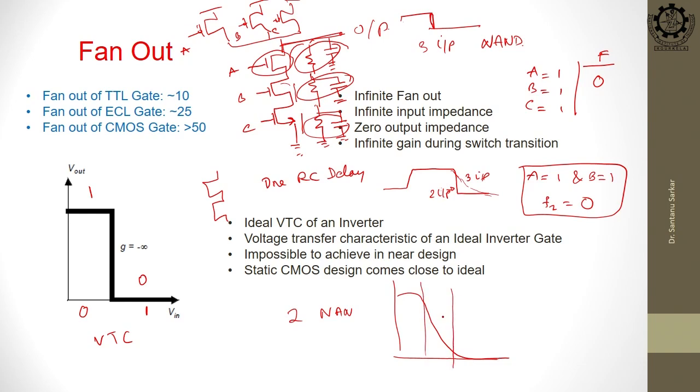This is the zone that we want to avoid as a digital designer, but this is the zone where the analog designer will try to find linearity. If you have an inverter and give a very small AC signal, you can amplify it, but the signal should be very small. If it is a little bigger, you will get a digital signal, you no longer get an amplified signal.